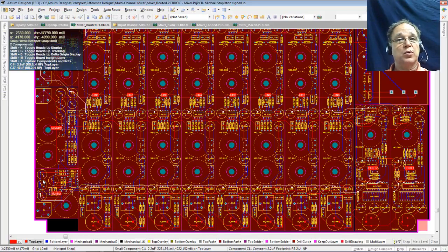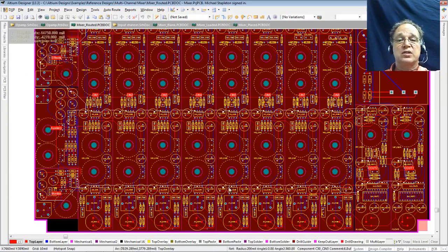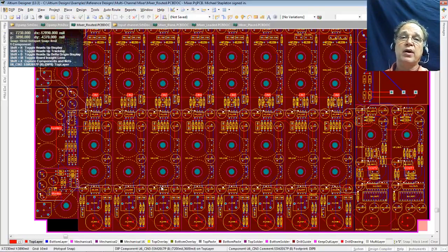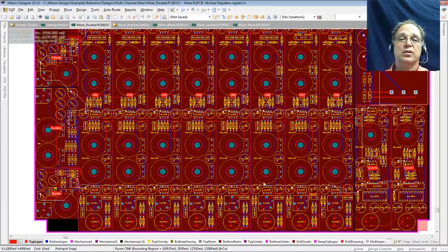Now remember, Ohm's law works for megaohms. It also works for milliohms. When I look at this long, thin little piece of copper wire, it has a DC resistance. As I draw current, the farther along I go, the lower my voltage will drop. As well as, that's about 3 feet or so of trace, I'm going to have some inductance.